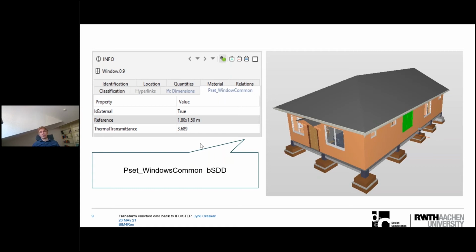But you need to recognize that when you are adding some values, they are in the ASCII file connected to property sets with standard property sets. And then when you're updating values, of course, it's very easy. You can find the property set where to apply the change. And when you are removing a property, it's as easy. You can remove the one. You can find the one by name. Of course, if it's the last one in the property set, you need to remove the property set also from the file.